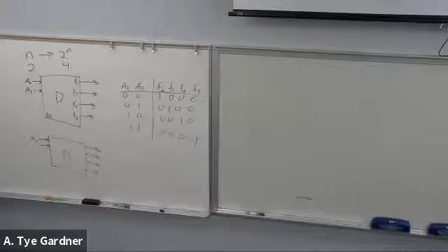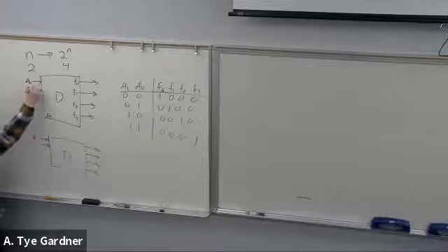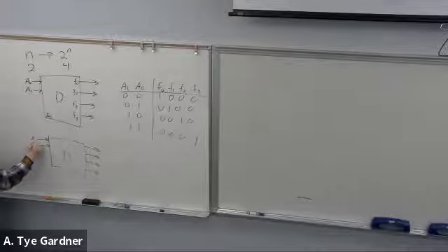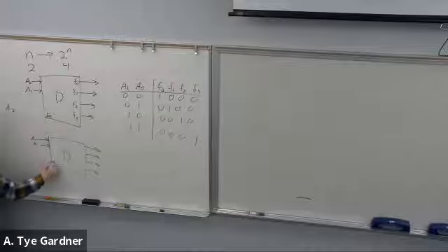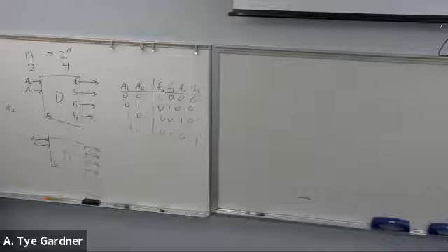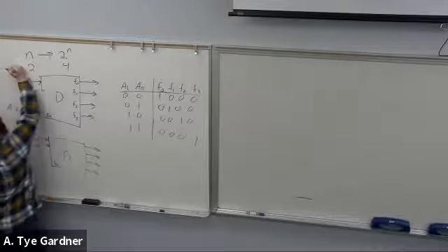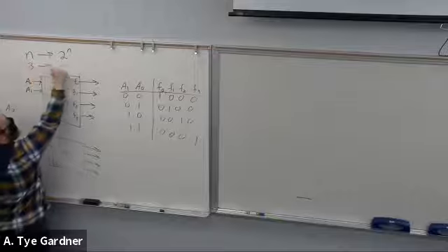One way that you could do this is, we're going to have 3 bits here. And I'm going to reuse A0 and A1 on this guy. And then A2, the third bit, is either going to go into this enable or this enable, because I only want one of these decoders turned on at a time, right? Because I want only one hot. So changing this from 2 to 4, we're going 3 to 8.